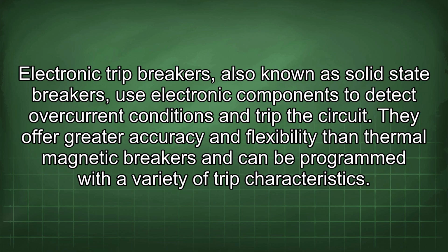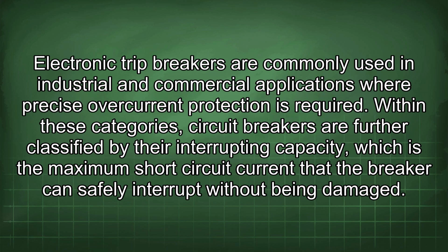Electronic trip breakers, also known as solid-state breakers, use electronic components to detect overcurrent conditions and trip the circuit. They offer greater accuracy and flexibility than thermal magnetic breakers and can be programmed with a variety of trip characteristics. Electronic trip breakers are commonly used in industrial and commercial applications where precise overcurrent protection is required.